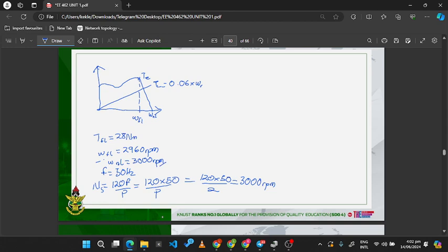As for no load, clearly the torque is equal to zero, because at that point there's no more acceleration, so there's no need for torque anymore. So I think this would also neglect the friction and windage torque. So the torque would be just the accelerating torque, and if there's no acceleration, then our torque will be zero. Okay, so we need to find the equation of this line.